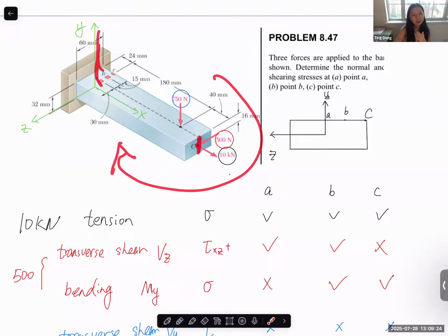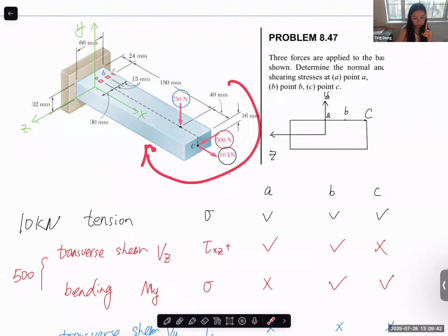Well, you can say that it's perpendicular to the force applied, but I think a better way to explain this is that the neutral surface on the cross section is always in the direction of the axis it's bending about, right? Because I can apply a force that generates this bending moment. I can also apply a couple here directly. There's no force.